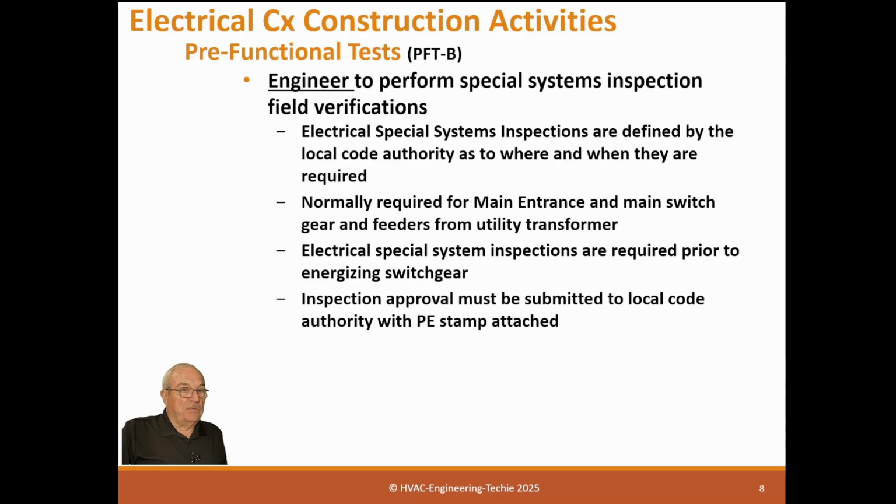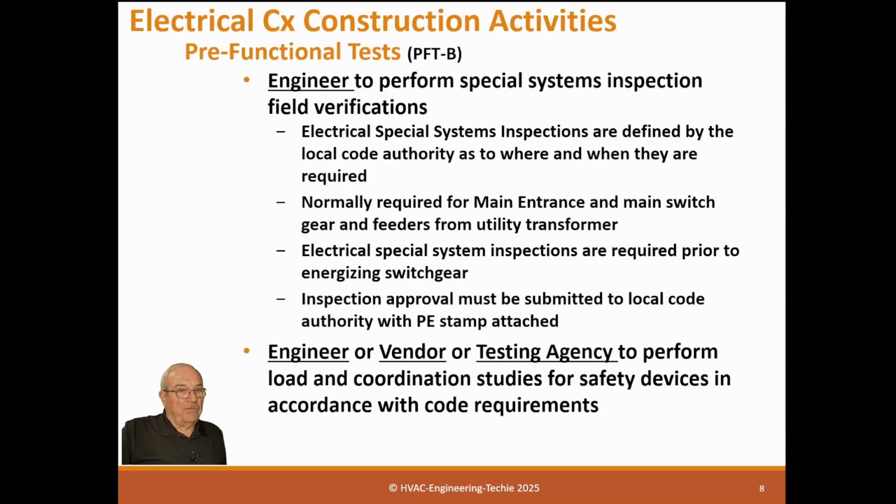The inspection form must be submitted to the local code authority with a PE stamp attached. So they're serious about making sure this is okay. Now, downstream of the switchgear, we can test that later. But upstream, that's important. Engineer, vendor, or testing agent performs load and coordination studies for safety devices in accordance with the code requirements. So normally, a vendor does this coordination study. An engineer might do it, or the testing agent can do it, but normally it's a vendor.